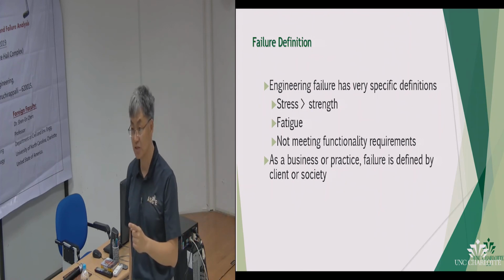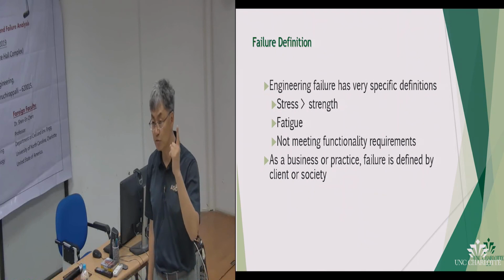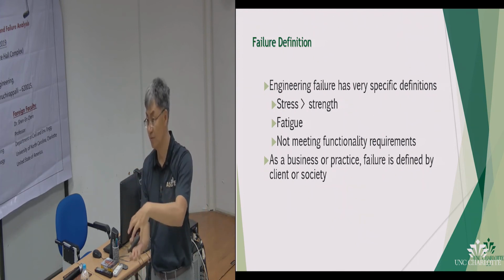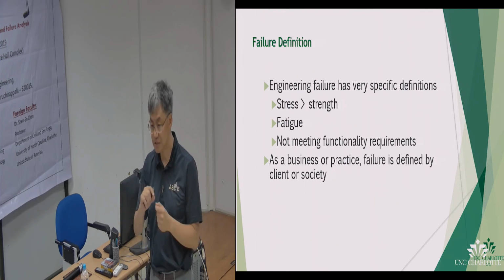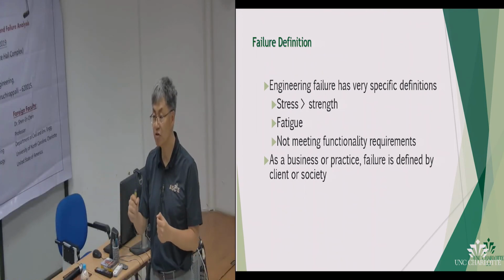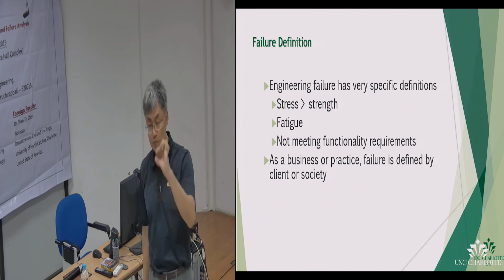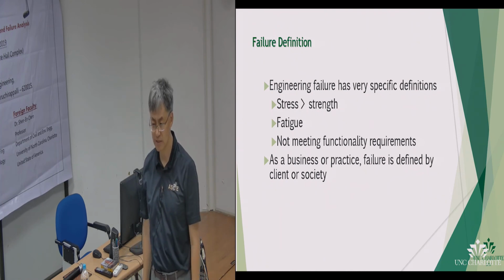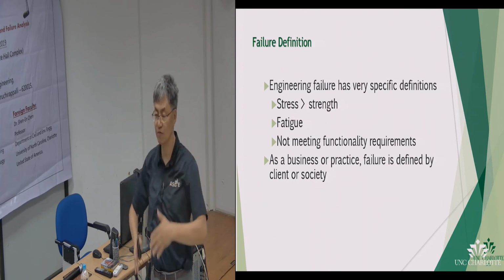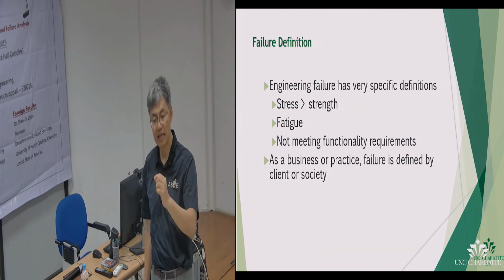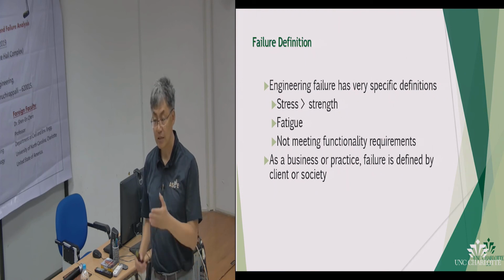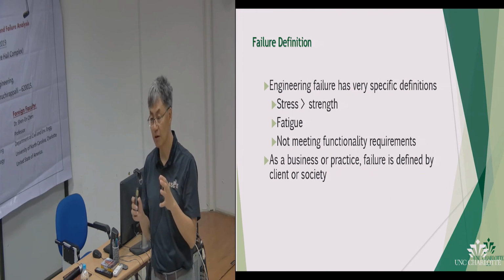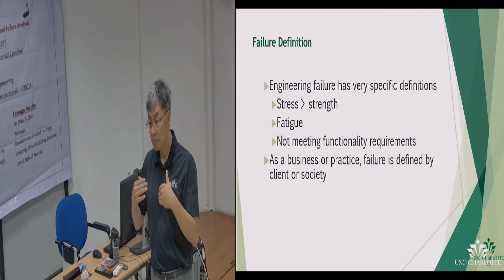From a measurement science perspective, we never measure real stress, because stress cannot be measured directly. The only way to measure stress is by putting a strain gauge on a calibrated load cell, right? So the only thing we measure in real life is deformation. And even deformation is not exact because a strain gauge is only this long. You put a strain gauge on a column, you are measuring deformation over this much. The rest of the deformations are just assumed. Does that make sense? And we know that the stress distribution is not uniform. So whatever we measure with a little strain gauge, we extrapolate our understanding. So measurement science is something that forensic engineers need to know very, very well.